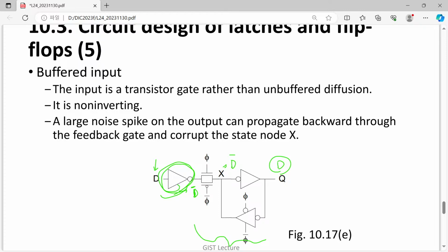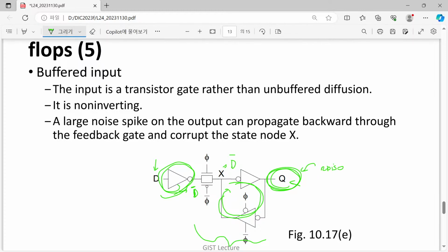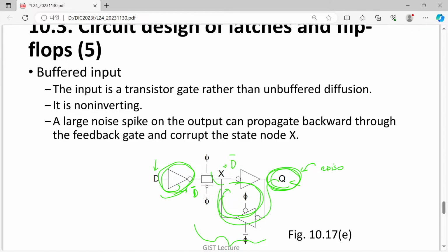Finally, please have a look at the last line. Okay, good. But if we use this Q as output, actually we have here a feedback loop. If we use this intermediate value directly as output value Q, then if we introduce a certain noise signal into it, this noise will just disturb the X value.